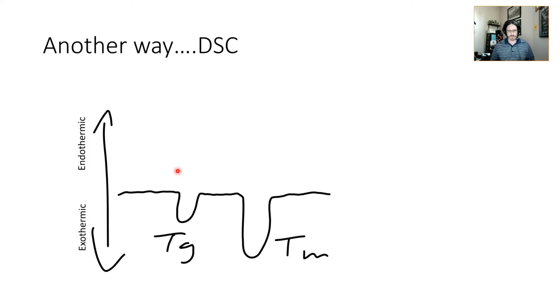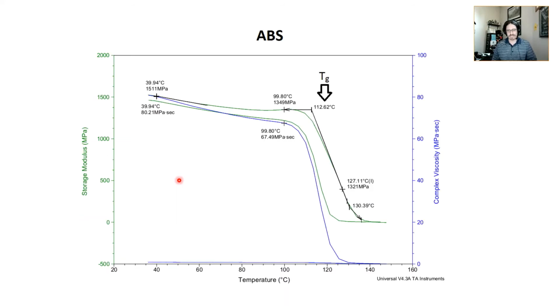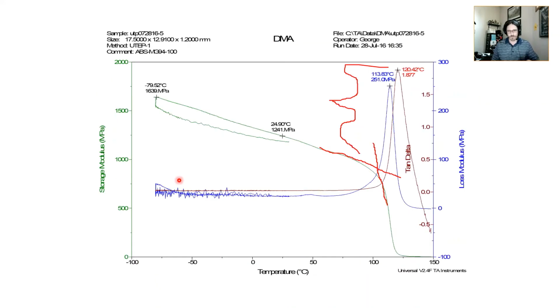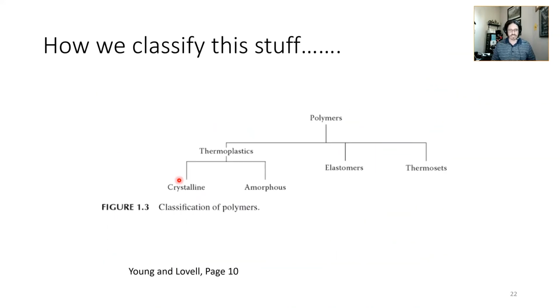There's a problem though sometimes with polymers in that seeing the TG exotherm isn't always that easy. It doesn't always show up, and I've worked with other colleagues and I've given them materials and they can't find a TG exotherm for me, even when I give them a window where to look based on DMA data, and they still can't find it. So I've been told DSC is the way to go, but I really like DMA for the data I need anyway. Someone else may be different.